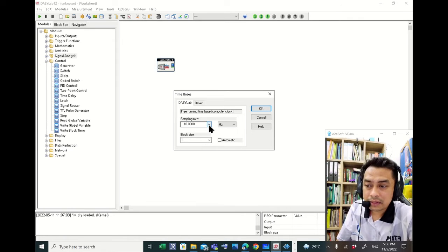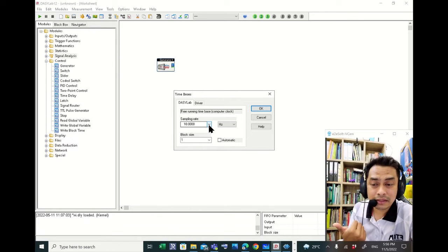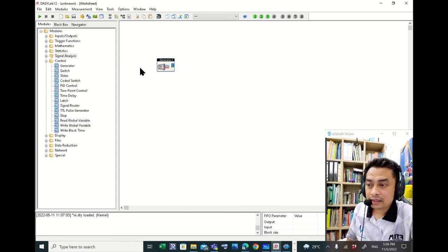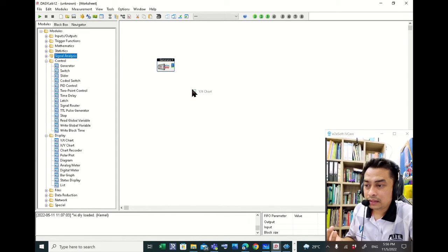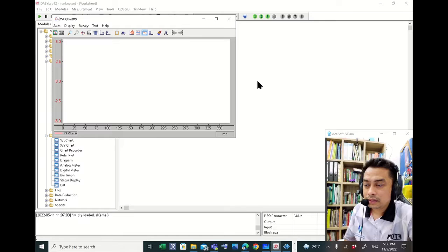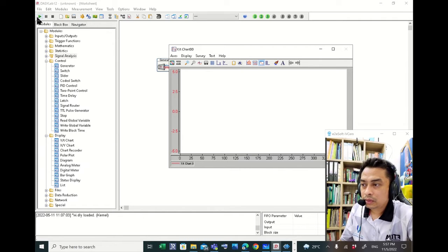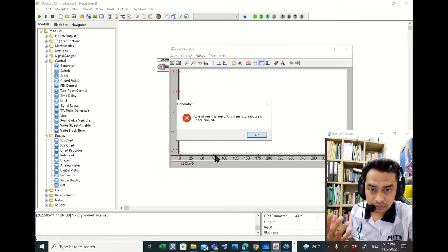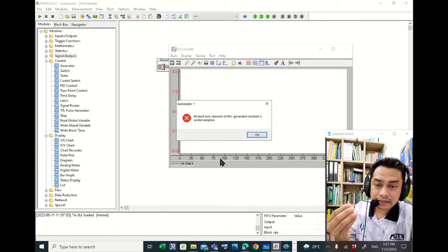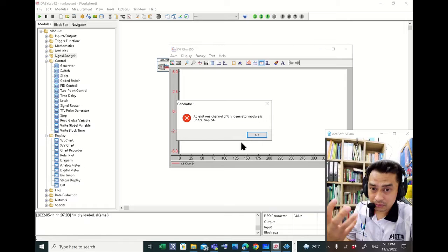So am I satisfied with the 10 Hz? Basically, I just set up a generator to generate 10 Hz. Theoretically, I cannot sample at 10 Hz. The system will not allow it. I can try and see. So if I connect a YT chart here, I will explain about the YT chart later, and open this one. If I run, it will not allow, because the sampling rate is the same as the frequency of the signal. So it's not allowed.